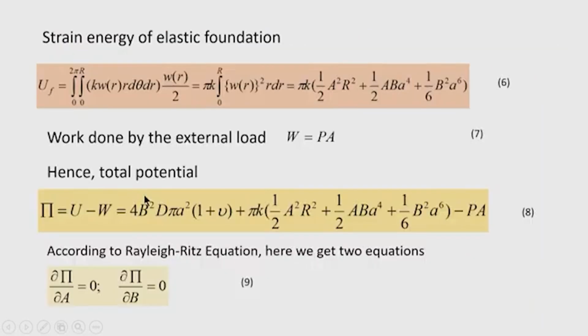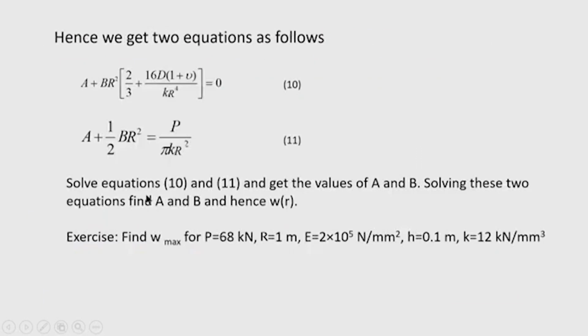So, this will be an approximate deflection of course, because it may not satisfy the boundary conditions at the edges, which are very difficult boundary conditions, that is the edge moment as well as edge shear both have to be 0, because it is the free end. Okay. Now, as an exercise you can calculate the numerical value of this plate problem.